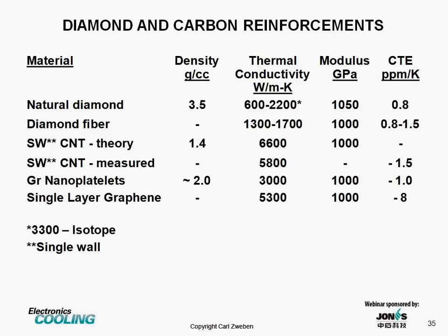In this chart, we look at the thermal conductivity, modulus, and CTE of various forms of carbon reinforcements. Natural diamond particles have thermal conductivities as high as 2,200. Notice the asterisk. There is an isotope of diamond that has a measured thermal conductivity of 3,300.